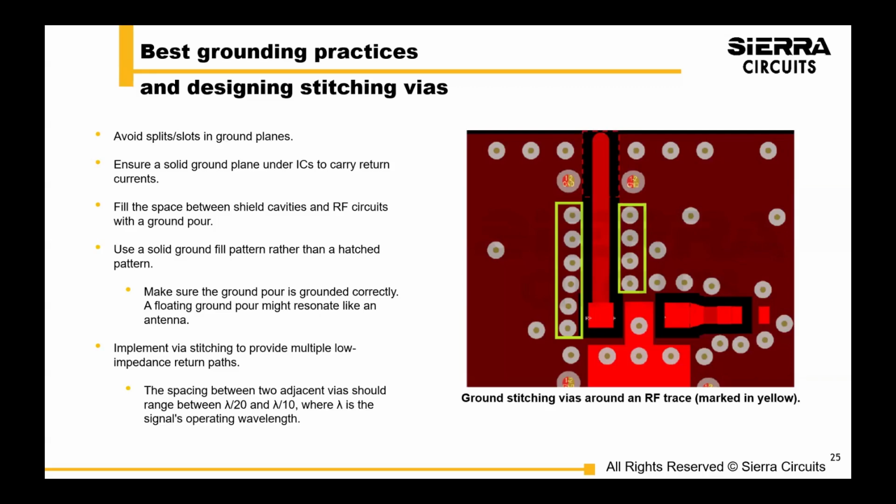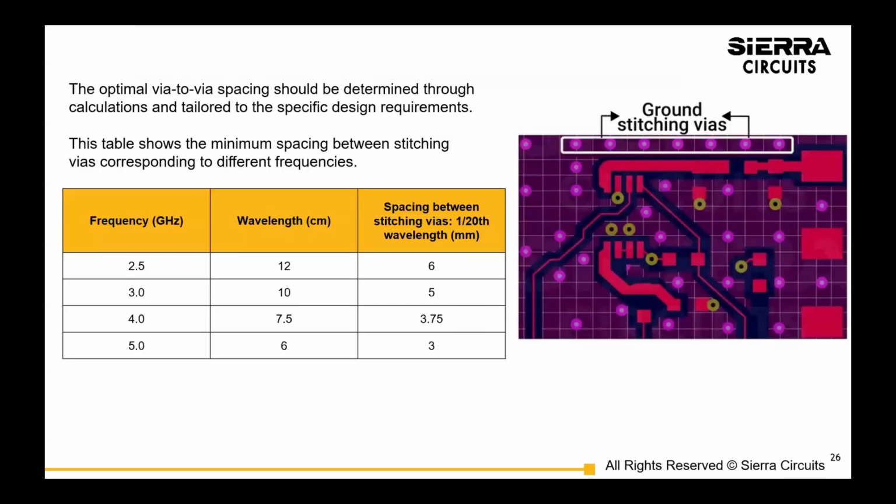One thing about hatched patterns, so we probably have in our design guide, use hatch patterns for flex boards. But the truth is, if you're only bending the flex once to install, maybe a hatch pattern is not needed. And so you'll get better performance if you don't use hatch patterns.